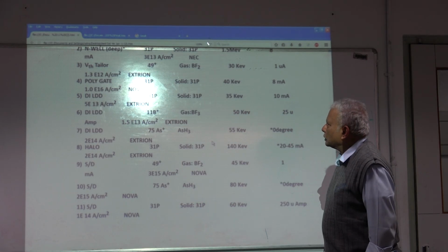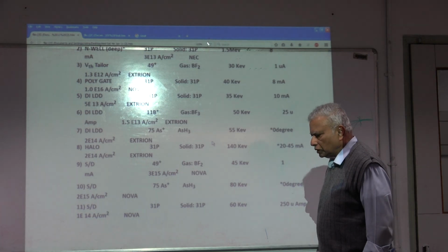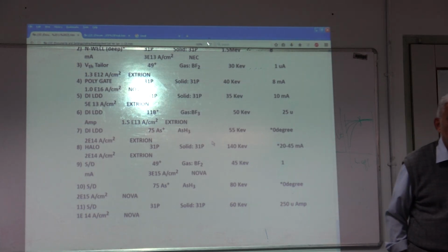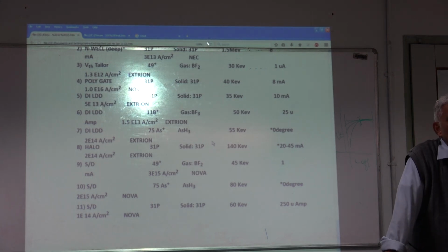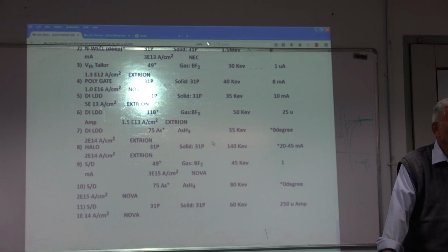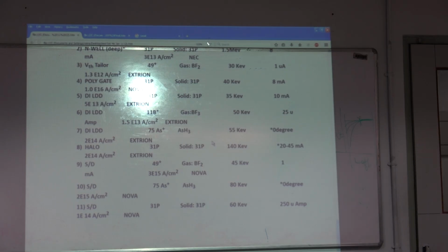So, just to give you the flavor, ion implantation is the method of diffusion today. Gone are the old days of doing diffusions of impurities. Our control is getting much tighter because we have many more available low energy implanters, and we're doing very tight control of impurities in very localized ways, and we are annealing them out. There is one thing I forgot to mention and did not put in here. Oh, we'll talk about it. In fact, I will add to it next.